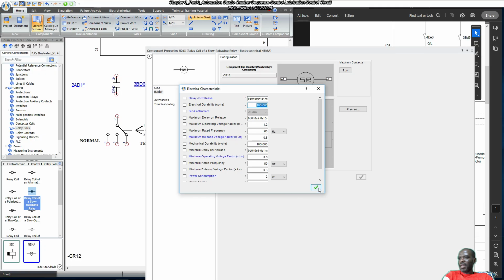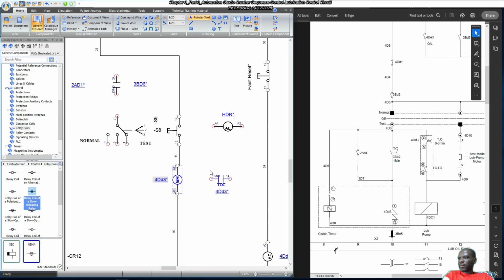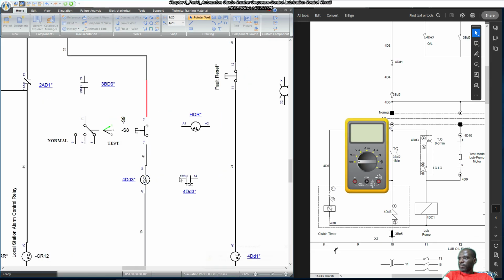All I need is a delay to open effect, okay? That's all I need. So I've put 1 second, see what we get. So let's see. Again, close this position, instantly close, open this, 1, 2, 3, 4, 5, okay, right about 5 seconds. So a second gives me 5 seconds. So that's the behavior that we were getting. So you notice that this is a delay to open, okay, delay to release.